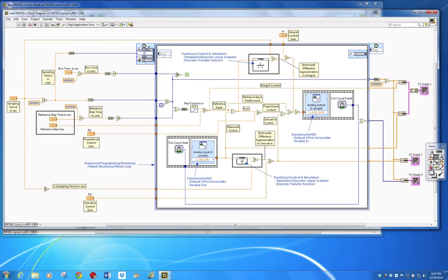At each execution of the timed loop, the tasks to be performed are: 1. Obtain the current measurement. This is the current measurement of the analog plant's output signal and requires an A to D conversion. 2. Obtain the current value of the reference input signal. 3. Process the current value of the reference input signal through the reference input feedforward control signal path. 4. Generate the current error signal by subtracting the current value of the measurement from the current value of the reference input signal.